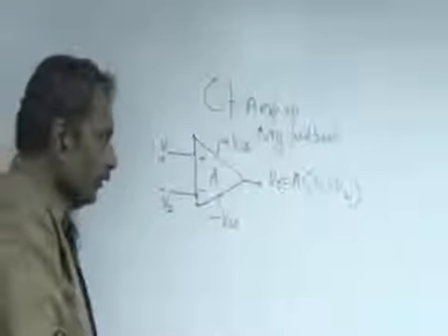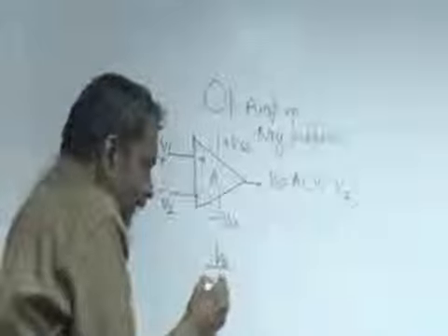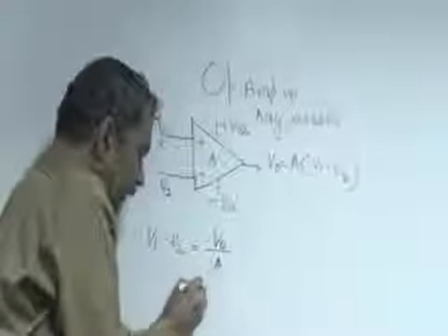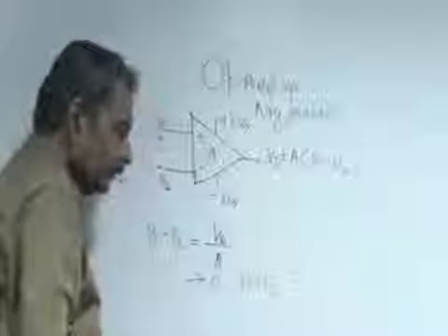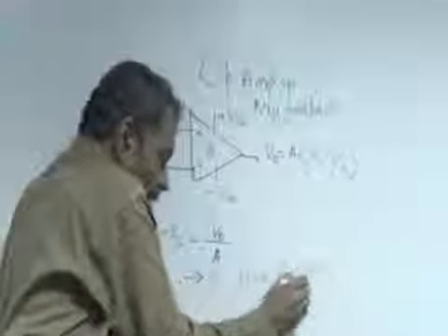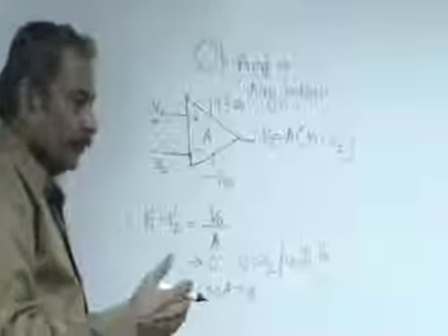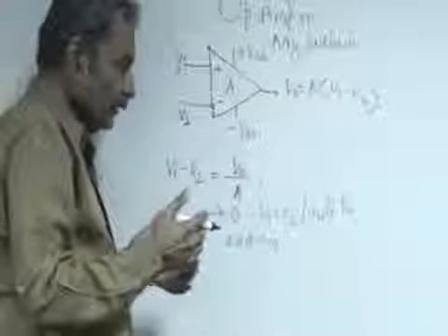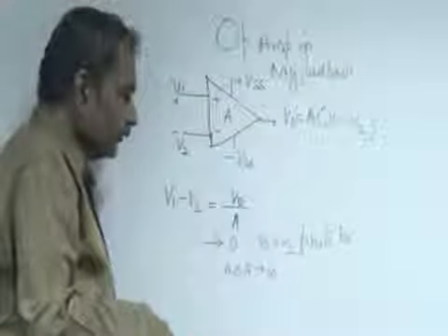is zero. Now with this kind of op-amp, as V0 is kept finite, V0 by A, which is nothing but the difference in voltage at the input, tends to zero, or V1 becomes essentially close to V2, for any finite V0 as A tends to infinity. This could be a current amplifier. Again, with the same current gain, as it tends to zero, I1 tends to I2, or the input differential current goes to zero.